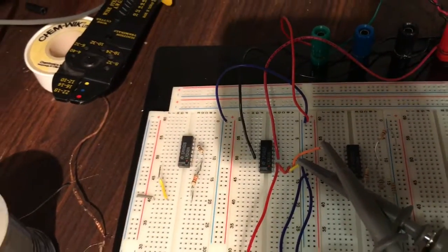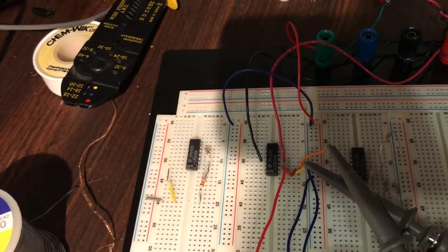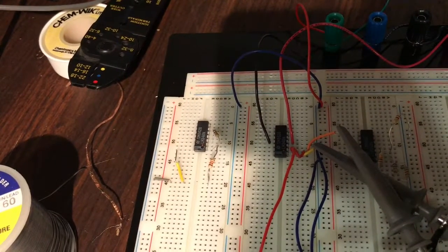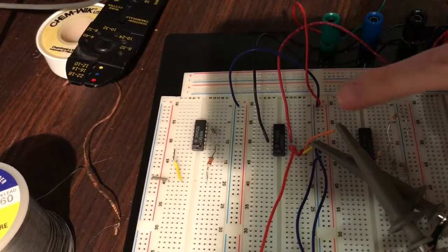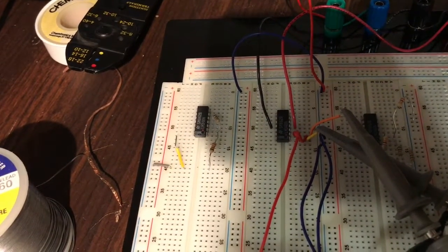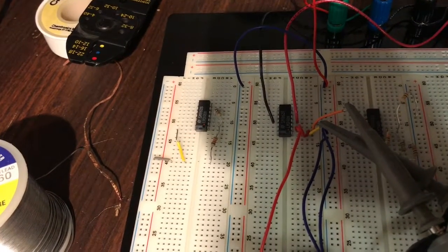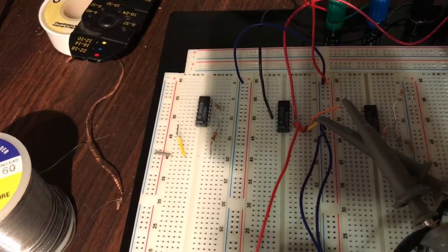So this is my voltage follower circuit, which is a unity gain non-inverting circuit where R1 and R3 equal infinity and R2 and R4 equal 0. So it's set up here with the positive input of the amplifier just connected to a wire, and the negative input is actually connected to the output of the circuit.